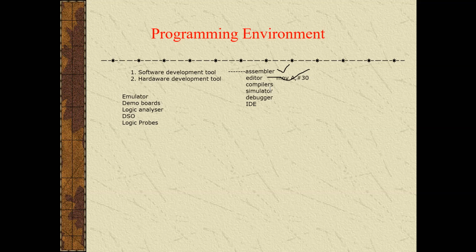So for the microcontroller family PIC 18, MPLAB will support writing programs and the assemble operation, everything. All the source code can be translated into object code there, and it also provides an object file and is needed for debugging with the emulator system. It has a macro assembly capability and supports decimal, hex and octal source as well as the listing format.